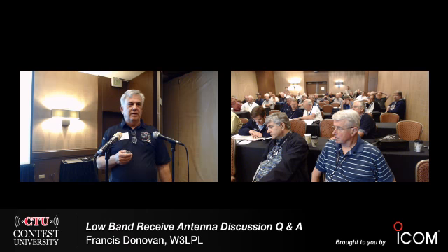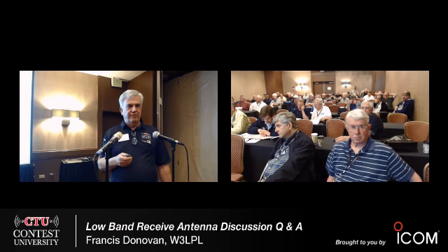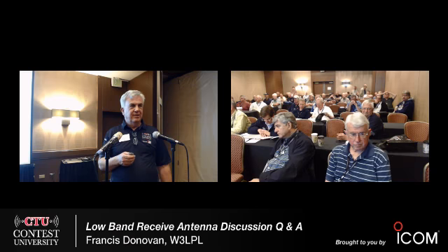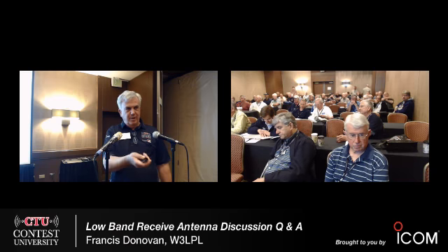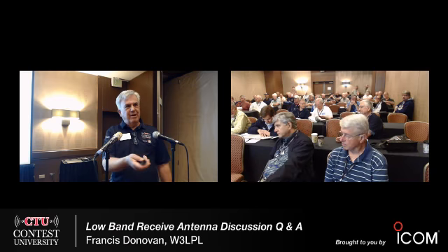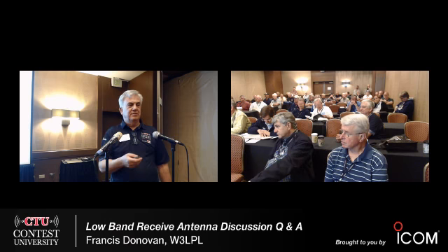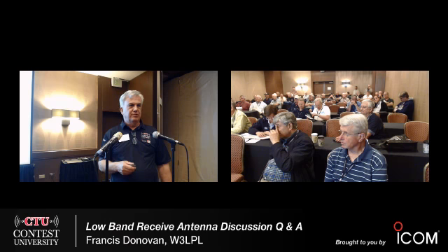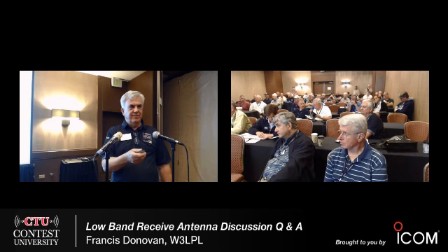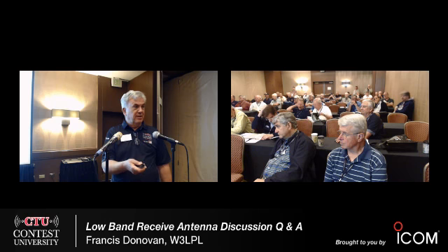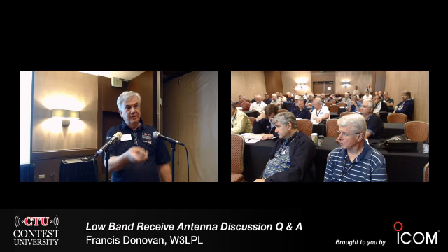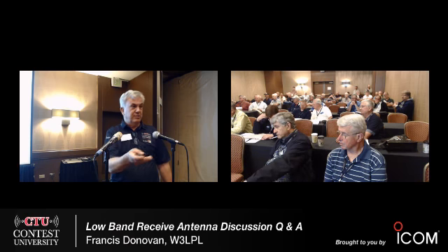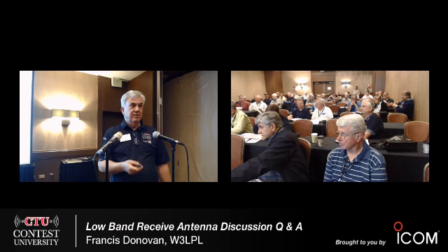Okay, so the question is, I'm going to put a very high gain amplifier on my loop. Am I going to have other problems from nearby strong signals? And the answer is yes. They're very susceptible to strong signals. If you have that kind of situation, it's wise to talk to the manufacturer first before investing a lot of money in it. You can tell him the distance of the broadcast station or whatever else, and he can tell you whether it's going to perform well.